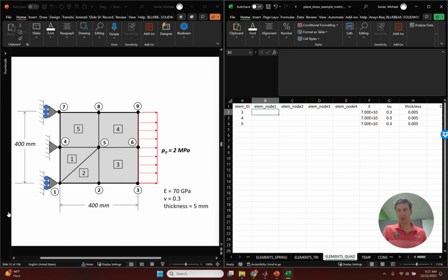And still we have to be careful about, with all these plane stress elements, that we have this counterclockwise ordering. And that's true for plane stress elements, and then if you start learning about 3-dimensional elements, there's a specific node order expectation that the solver will expect. And so it's true with everything, but with our plane stress elements, it just needs to be counterclockwise.